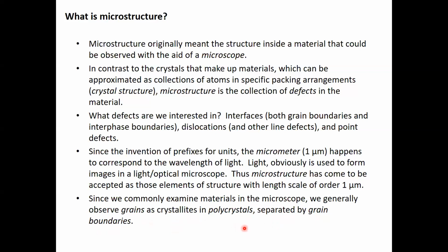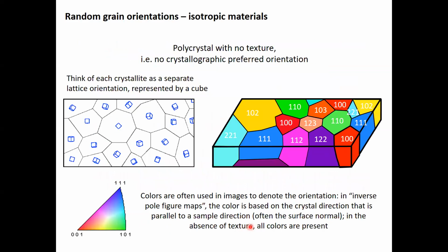from, right? When you have a random material which is just cast without any directional flow of the liquid material, the material crystallizes in this polycrystalline form, where each of these polycrystals is its own single crystal, and they are all oriented in different directions. And these directions here signify a close packed direction of that crystal structure. You can quantify that using electron microscopy, and as we saw, electron backscattered diffraction pattern.